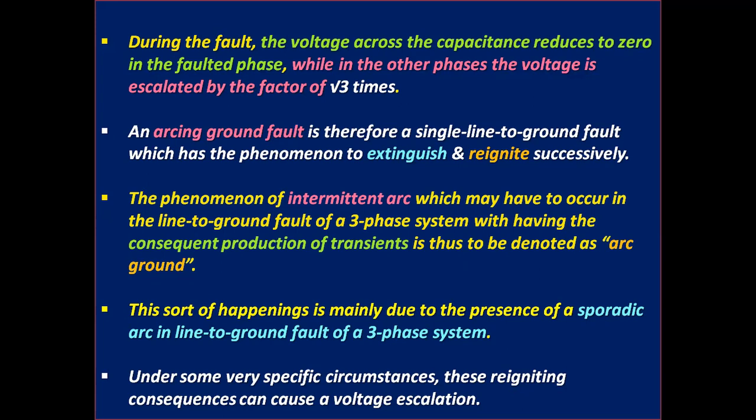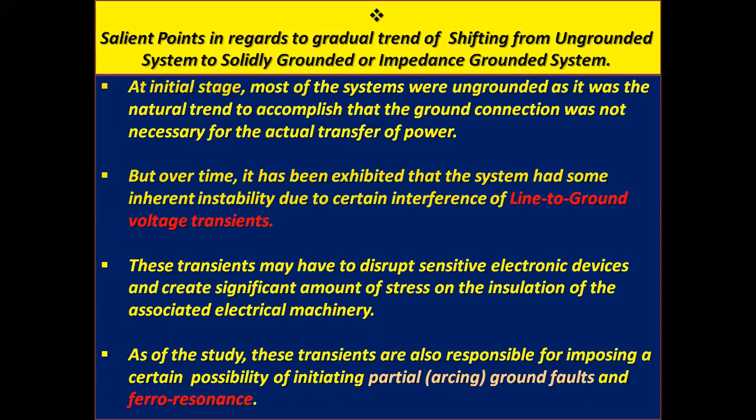Most important salient points in regard to the gradual trend of shifting from an ungrounded system to a solidly grounded or impedance grounded system. At the initial stage, most of the systems were ungrounded, as the natural trend was to assume that the ground connection was not necessary for the actual transfer of power.